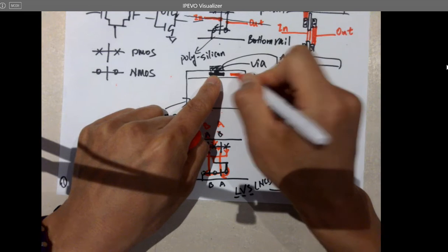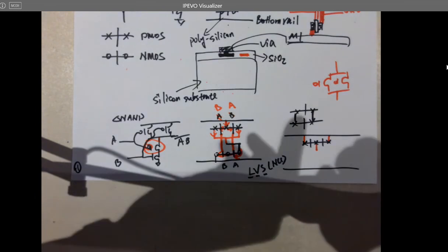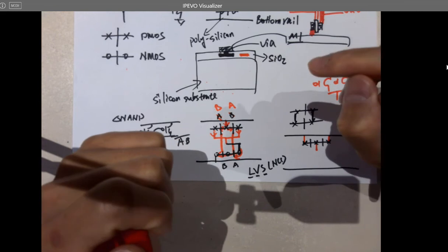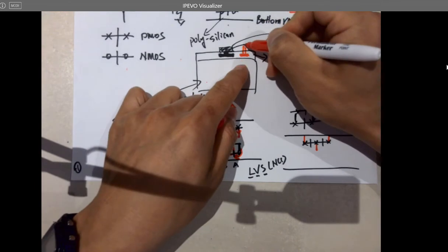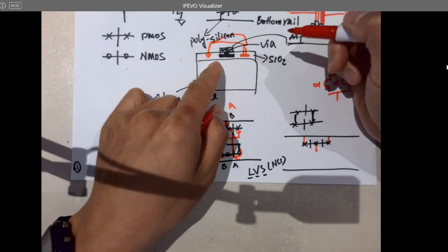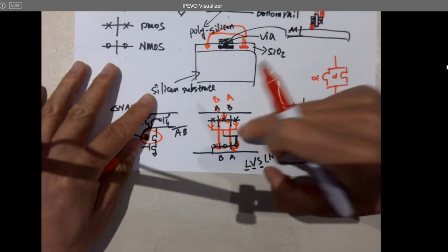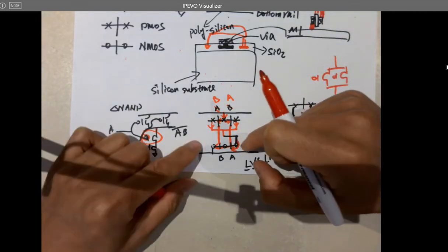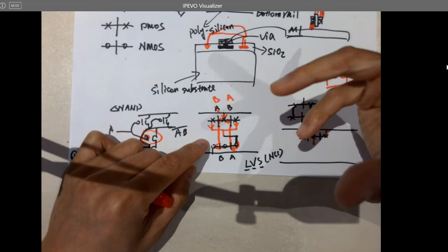You got a poly here as well. The same layer, you cannot get through it. Or if you get through them, you cross the two poly layers, they are going to be shorted, becomes one signal. Otherwise, you have to drill a hole to the top and run metal one on the top, and then come back to the poly layer again, if you don't want to short them together, but it's still going to take a lot of space. So for this case, you have many different options, but you need to be aware of the best practice regarding the space, regarding the length of the poly wires.